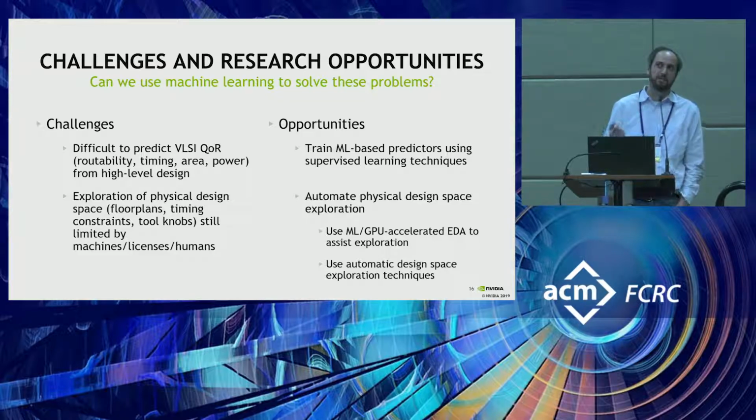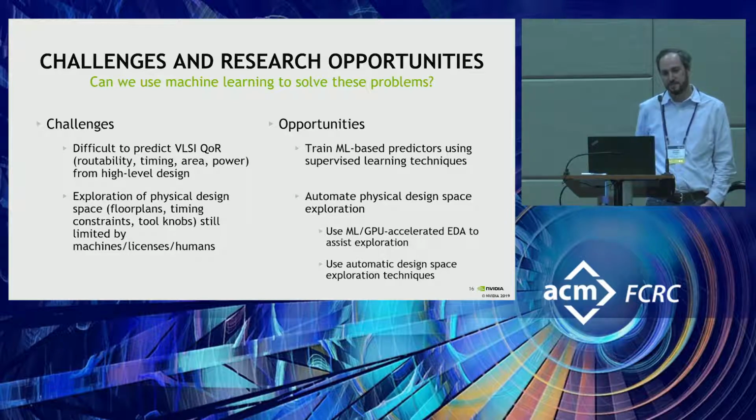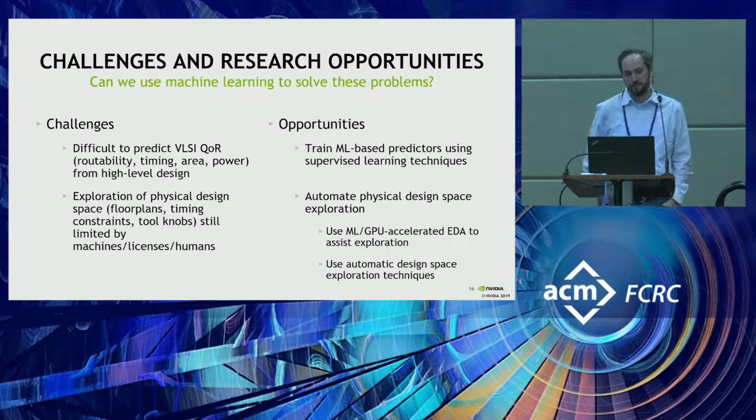The hard part was sometimes we would put something on our FPGA emulation system or run it through RTL and it would fail and be hard to repro in C++, but we eventually were able to do that, usually because we just didn't run enough cycles with random stalling or something in the C++ model. And once you could repro it, it was way easier to find and fix. If you find it in the source, it's easier, for sure. For sure, yeah.